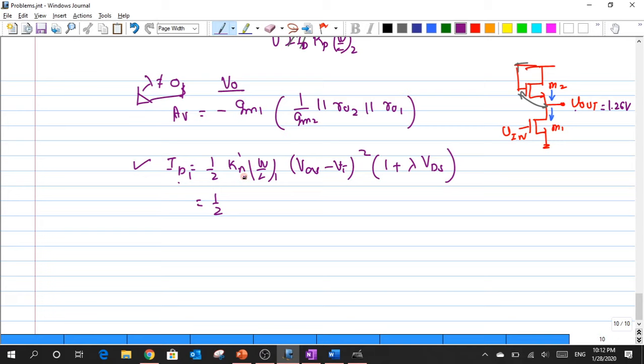So one thing that we have to ask is, can I currently make use of this equation to compute the value of ID? I guess I might not do so just because I have to encounter this Vout, right? So rather than working with this bottom transistor where I cannot encounter this Vout expression, what I do is that I'll just try to work with the ID2,